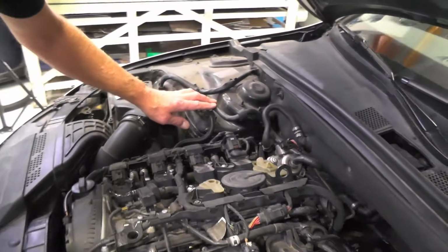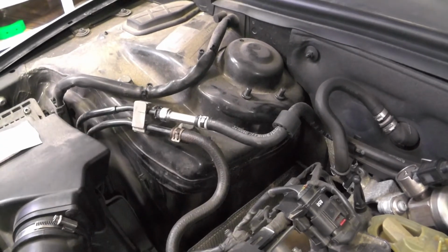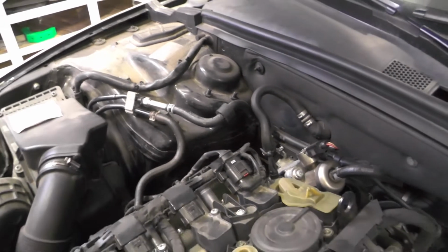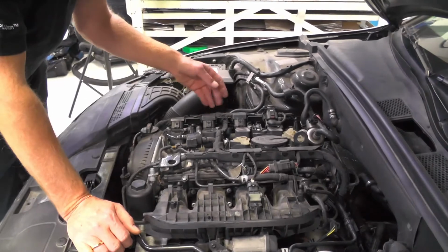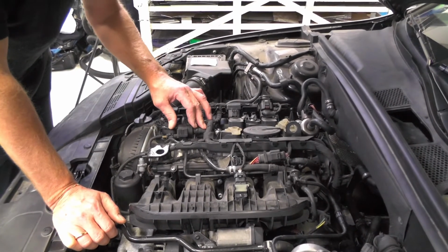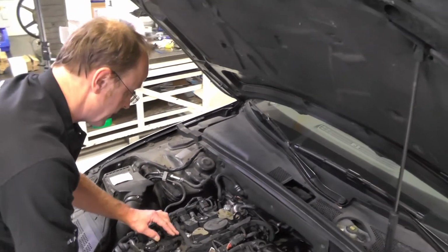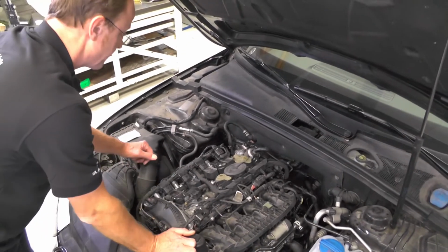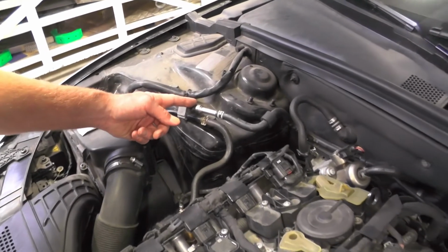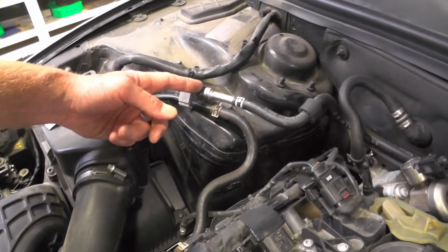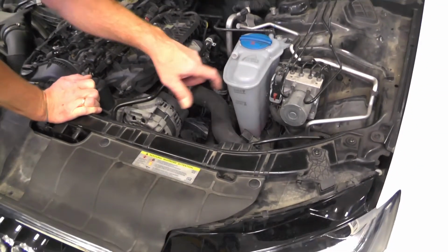This is important for applying a flow meter. You have to connect into the supply line that comes from the tank to the engine. And you have to check there's no return flow to the tank. The second line that you can see here is not a return flow to the tank, it's just a regeneration line for the canister that collects the evaporations from the tank. So this is the line we want to connect to, and this connector we're going to use later on for connecting the flow meter and taking lines over here where we then connect to the PLUtron.